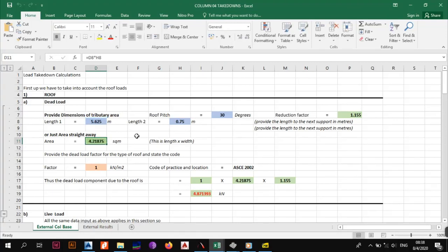Since all of these are areal loads and they're based on the contributing area, or the tributary area, the result was going to be the same. So that's the other thing. Whenever you find the results seem to be suspect, always go back and check whether your calculations are good. So this is the thing about checking your calculations.